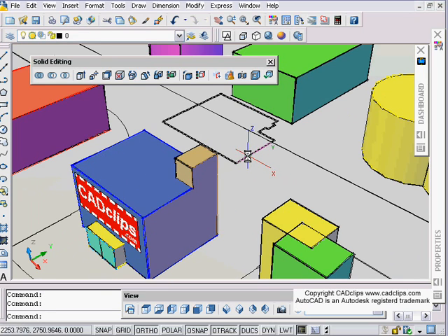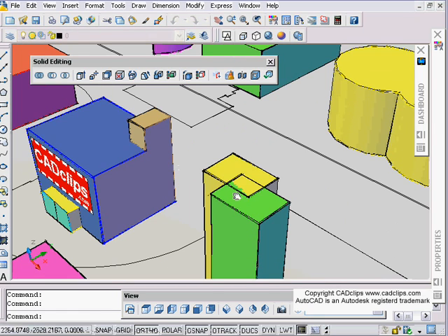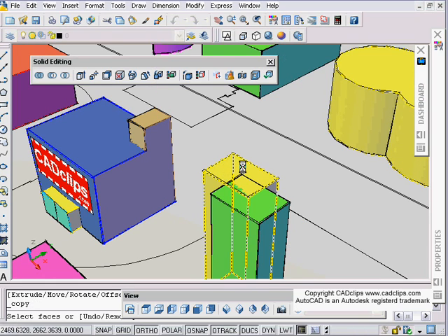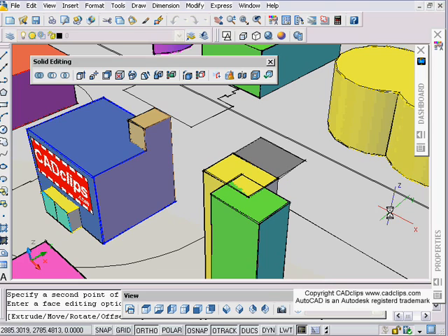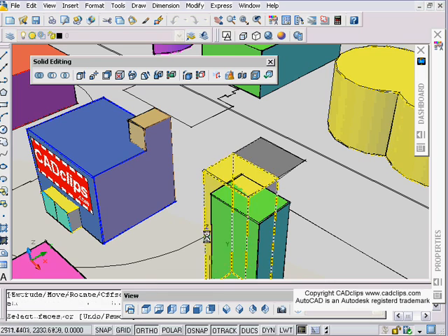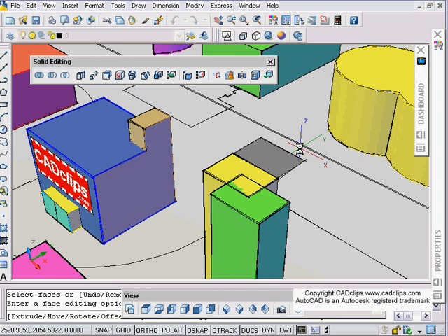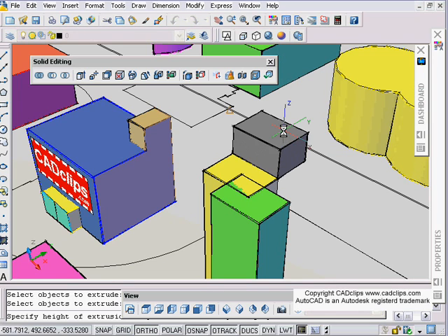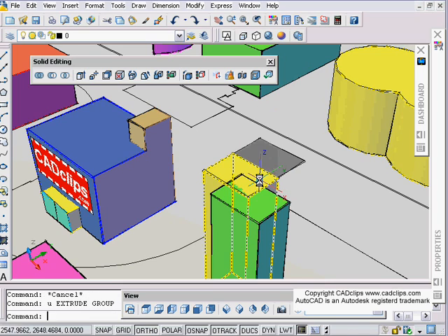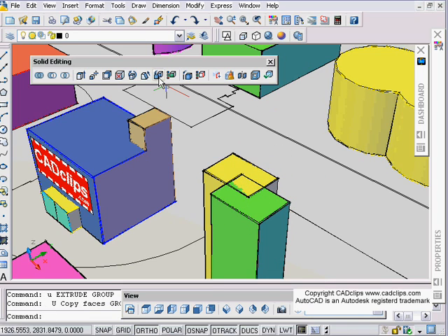And sometimes you're doing this because you're trying to create a negative geometry, or you're going to go in and try to do some editing inside of here. Okay, we can look at here, these two objects are not unioned together yet. So if I go inside of here, and use my copy face and I pick on the top there, enter, from this point to this point, I'm only going to get that one face. And then you can look at some other options down here, rotate, extrude, and then work that way up, or you can go just into here, do your extrude, and then take that for whatever reason. Okay, it's all a matter of just editing the geometry.